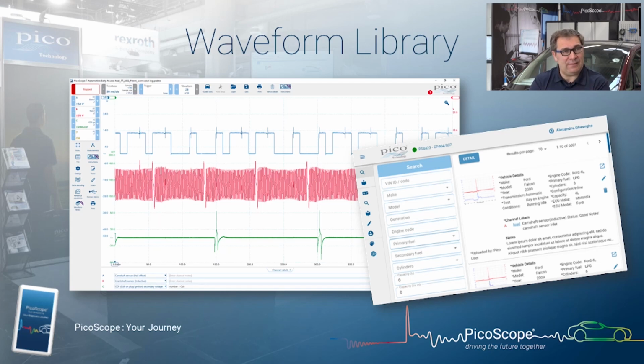So we log in and we've got all of those different pull downs that we can look at to find our vehicle. Even if you're lucky enough to have an 8-channel scope, you can have 8 channels of data that you can download, either the whole set of waveforms, or if you're only interested in, say, cam and crank, you can just download the ones that you want.